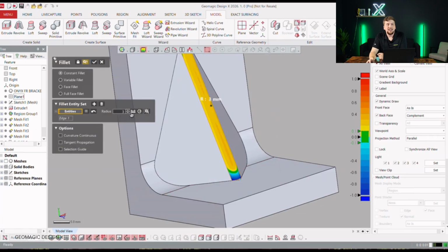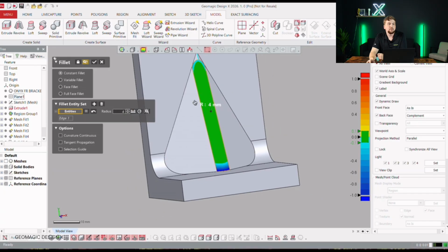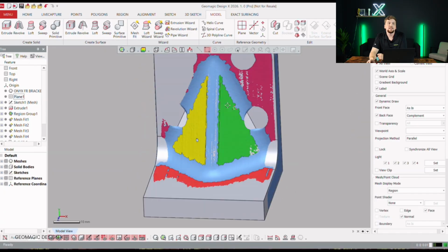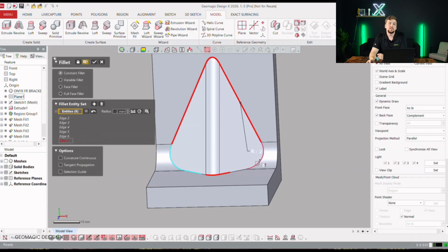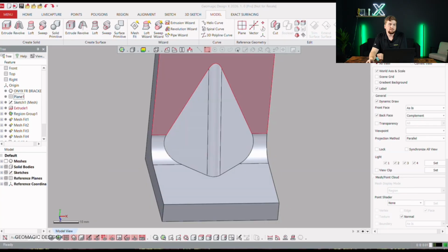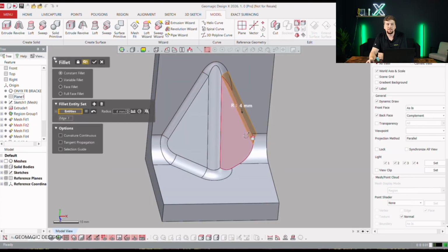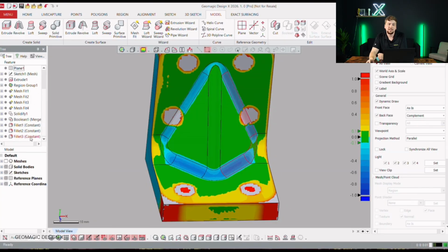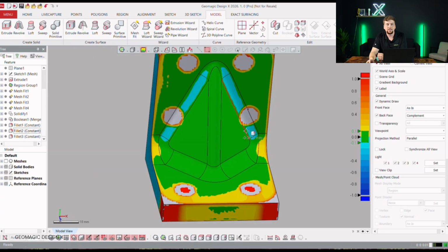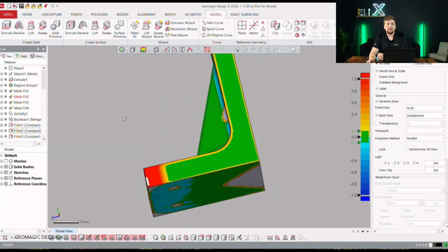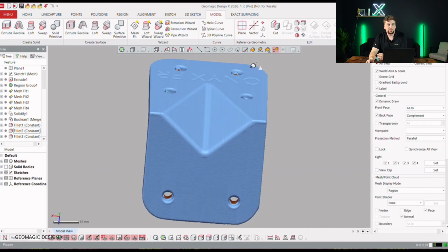Personally, like I said, I try to not rely on those. I will use the pink sketches for any of the abstract splines that are just really not a uniform radii or anything like that. I prefer to use conformed numbers like radiuses that are all pre-built standard numbers. It makes it a lot easier later when another engineer is looking at it and they're not trying to do any funky math, or they're not breaking their part trying to deal with your weird dimensioning that you have going on here. This bracket, as you can see, has some relatively loose tolerances.